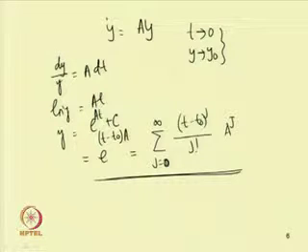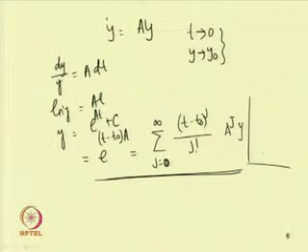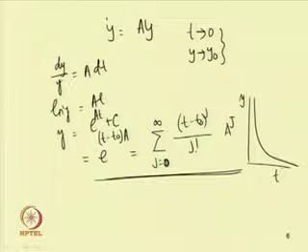If the real part of the eigenvalue is negative, then the response decreases exponentially; if one plots the y versus t curve, it will exponentially decrease. If the real part is positive, then the response will grow exponentially and one gets an unstable solution.